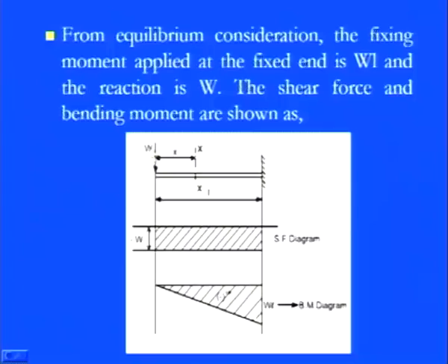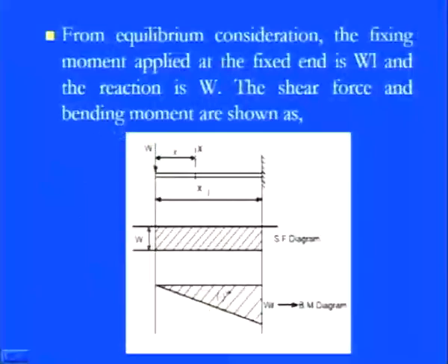So now you see, on the same beam, due to this applied load, if we have the bending moment, it will vary from the point of origin of this load and go up to the maximum where the fixed corner is. Because M is nothing but equal to minus W into x. So if we keep x equals 0, we have M equals 0. So at this particular point where the origin is, the bending moment is 0.